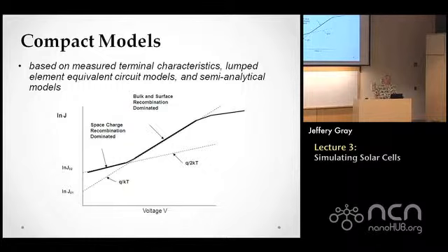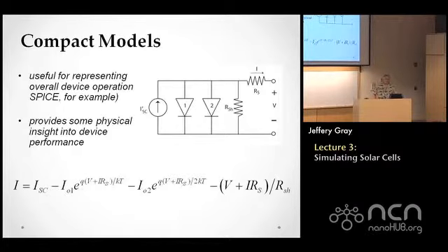They'll be based on some fundamental physics like the Shockley diode equation, which I'm going to show here in a second. But they'll give you some idea of what's going on. So they'll use lumped circuit elements and maybe semi-analytical models, which we'll see here in the next slide. And so a fairly common representation of a solar cell is what I've shown here.